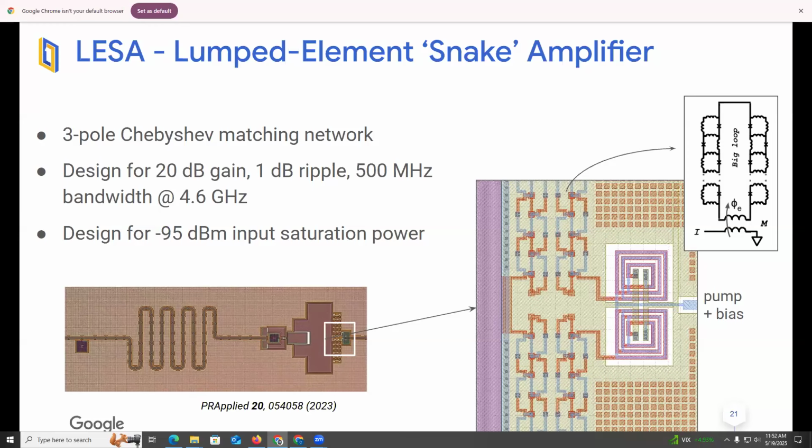You should still have a model for what kinetic inductance looks like in your circuit simulation, and be able to simulate that accurately in harmonic balance, for example, to figure out if you have intermodulation or saturation, and the stuff shifts on you when you turn up the power and stuff like that.